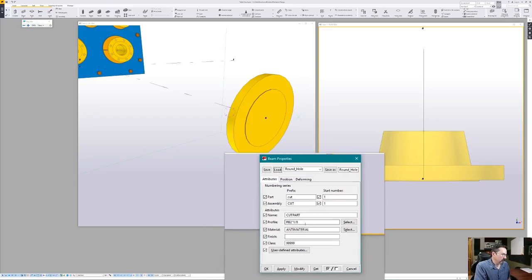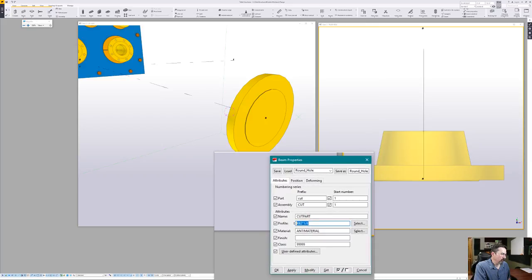Now for this I'm going to use the D part again. And the bore on this comes from that chart. It also comes from the inside diameter of a Schedule 40 pipe, which is a standard bore. And for this one, that diameter is actually 4.026 inches. So for this, I'm going to use the same diameter, the D profile, and then put in 4.026 inches.